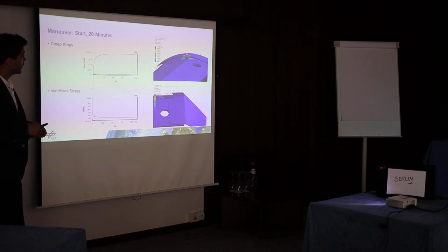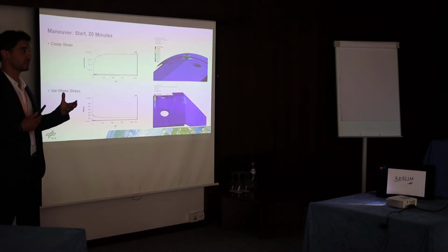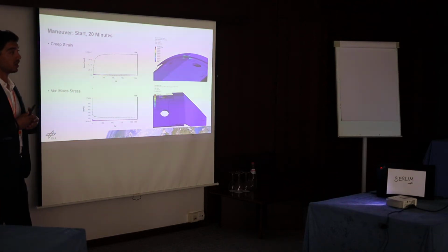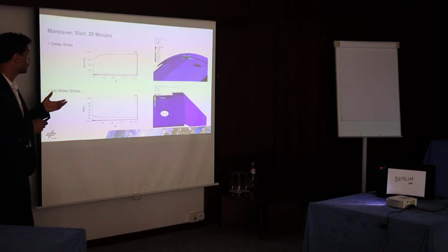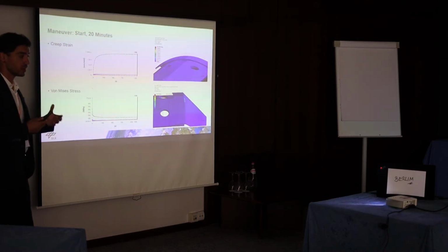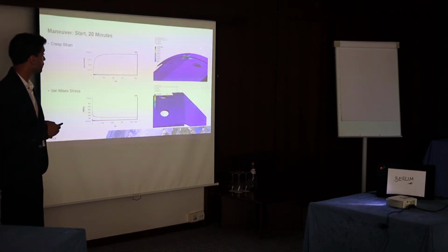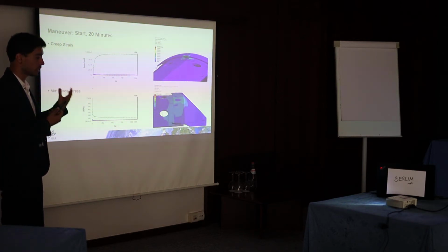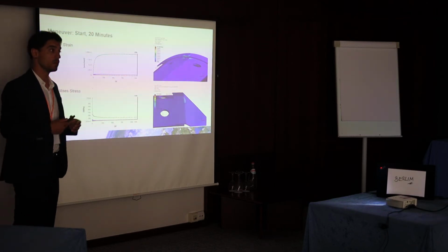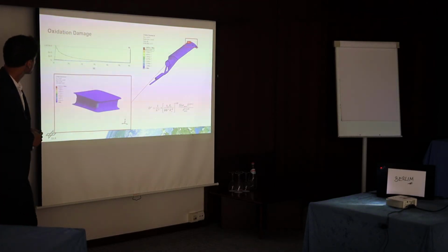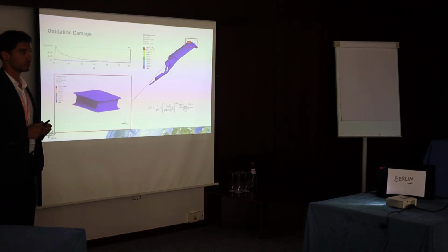We see also that in our geometry, the areas most affected by thermomechanical fatigue are obviously those where notches are present, so those where large geometrical nonlinearities are present, and those are places which must be investigated more thoroughly.